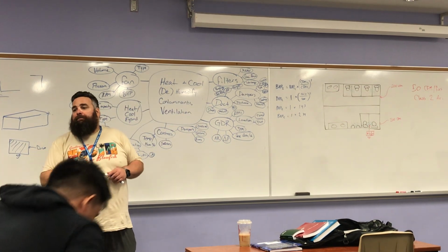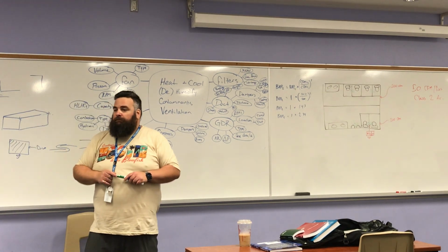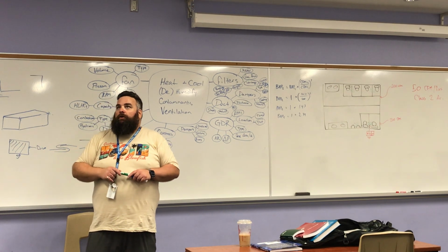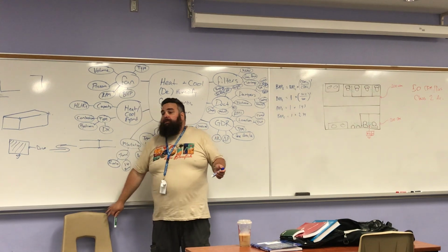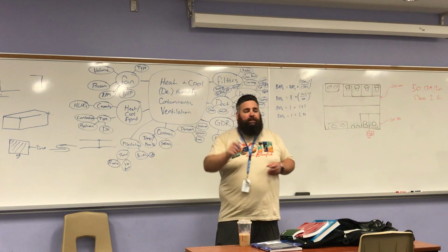What is the impact of going up through the roof? Well, if you have an intake above where the discharge is, then when it comes up, the intake will just take it back in. So if you did a sidewall. Yeah, if you did a sidewall, okay. So sidewall, I can mitigate it. Let's say I've got my 10-foot separation, so I'm not worried about re-entrainment. But let's start with the roof.